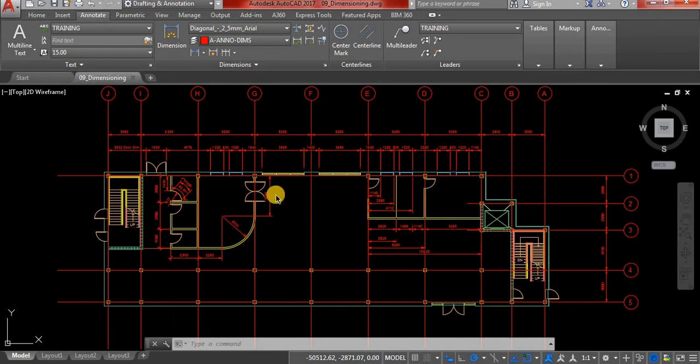Multileaders can be very useful, especially when you're working with mechanical objects and you want to point out several things as a bubble and you want to track attention to it. Let's go ahead and, to annotate, tap on the ribbon, and you see we have this section especially for multileaders. You can add one, you can remove one, you can align, or you can remove or combine.